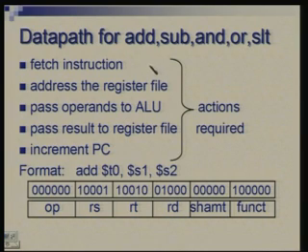This is only a subset of all the instructions which have a common opcode here. Then there is a source register 5-bit, and a third register 5-bit. So, these 2 are the operands, these 2 specify addresses of the operands, and another 5-bit field specifies the address of the destination. So, all these are numbers from 0 to 31, and specify one of the registers.